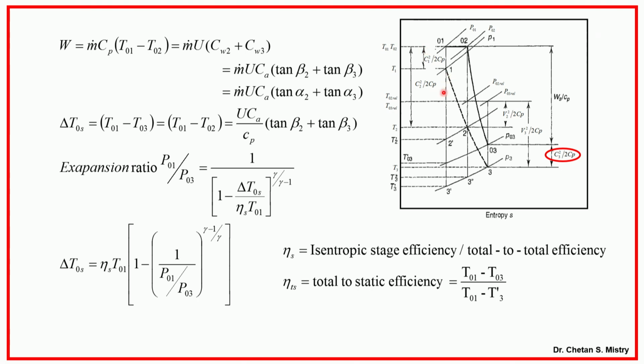Now the stator is not doing any kind of work, so we can consider that process as an adiabatic process, and that is the reason why we are assuming T01 and T02 are the same. But it is interesting to observe that my total pressure is reducing.